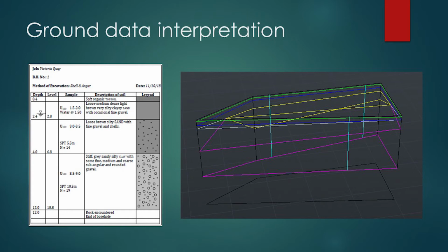Before we start our study, 4 borehole logs had already been done on the construction site. As those boreholes haven't been cast at exactly the same location of our foundations, we had to interpolate the ground conditions from the adjacent boreholes. So, to do that, we've created a 3D view of the soil from the borehole logs. This abstract object had permitted us to see the relation between the 4 logs and the continuity of the different veins of soil.